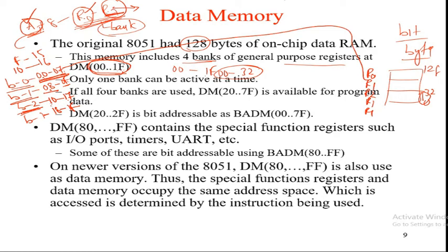In the 8085 microprocessor we write MVI B, 14. So move immediate data 14 to the B register, in the sense 14 data is transferred to the B register. But for this data, as it is internal to the microprocessor, no address representation is there. But for a microcontroller, everything is going to be defined with both data and address.